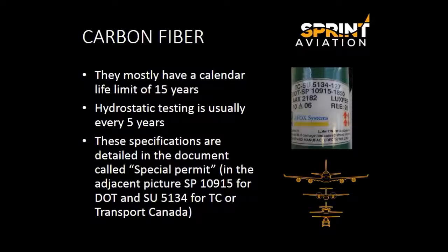Carbon fiber cylinders have a calendar life limit of 15 years. Hydrostatic testing is usually every 5 years. You may find these specifications on a document called Special Permit.